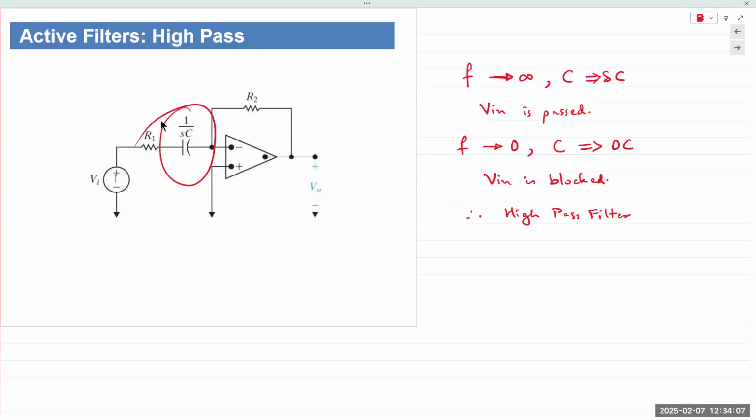So this is known as an active filter. You can impart a certain gain to your signal. If you simply use passive components, which are used in crossover networks inside speaker boxes, those are passive components. They do not amplify the signal. Active filters like these will filter the signal as well as amplify it. So most electronic circuits nowadays use active filters.